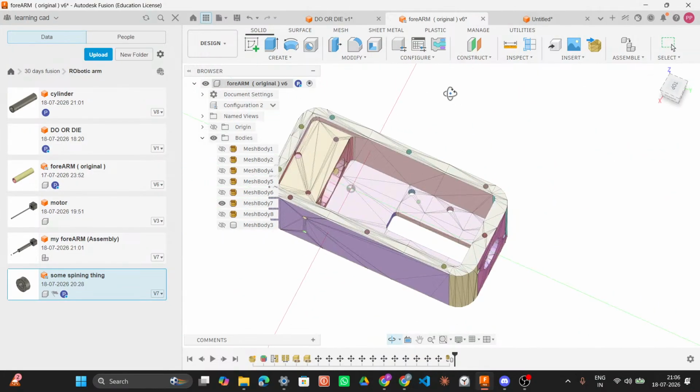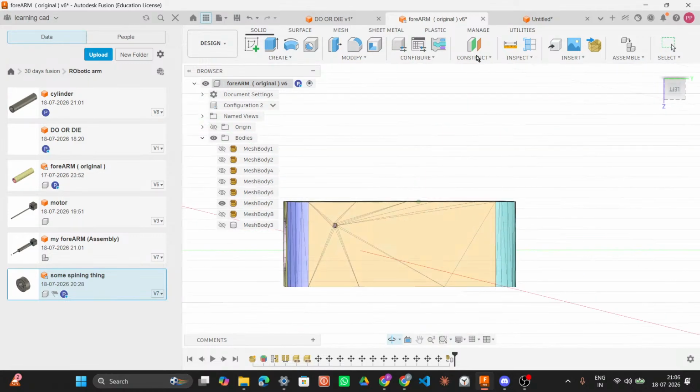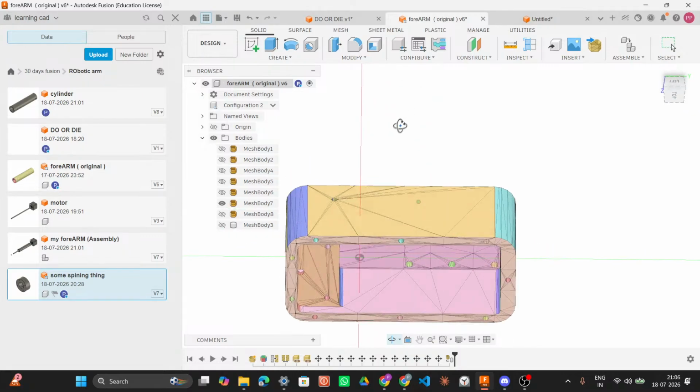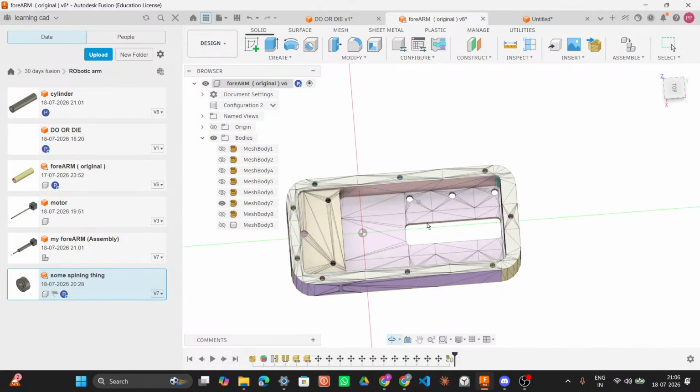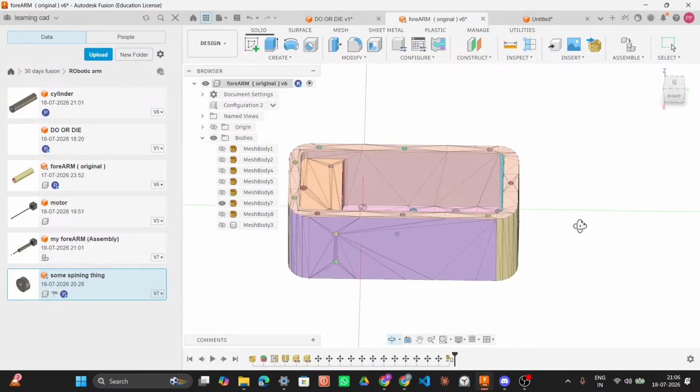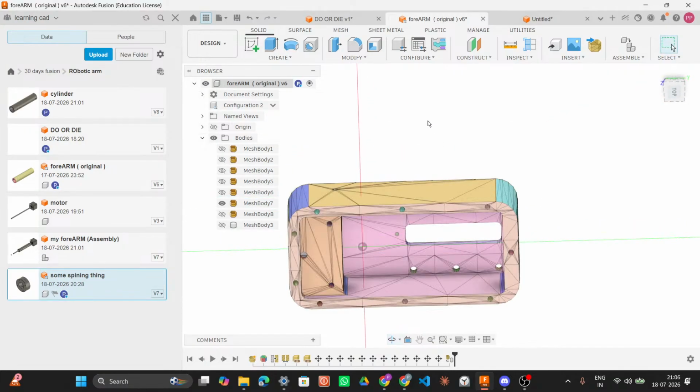I'll definitely use the thing that you said, to use the mid plane. Getting an intersection of the part is a lot of the time super helpful, and even if you don't do a mid plane, doing an offset plane like you're saying, you can do the same thing, and if you want to get a profile out of it at a different height to get specific geometry.